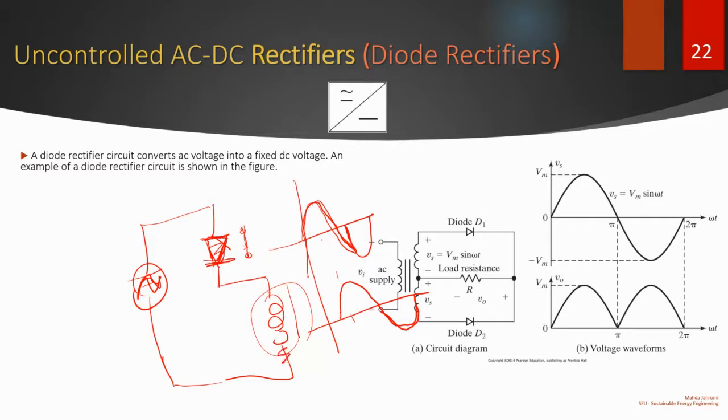Usually you have a resistor here as well, so it's not exactly 90 degrees, it might be like 40 to 50 degrees. So if I draw the current, the diode keeps on conducting until the current going through it is zero. Okay, so you end up with this kind of a voltage waveform.